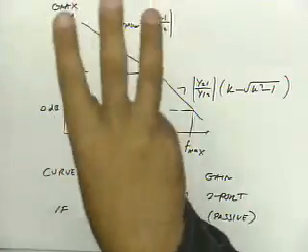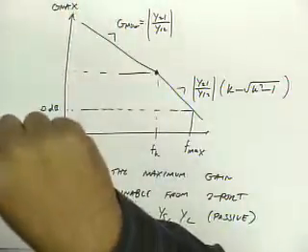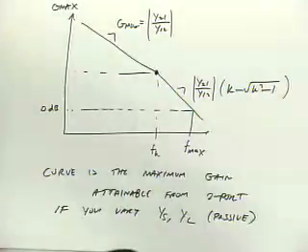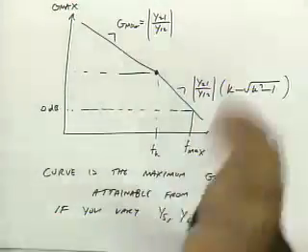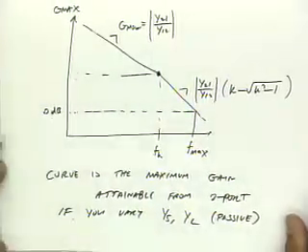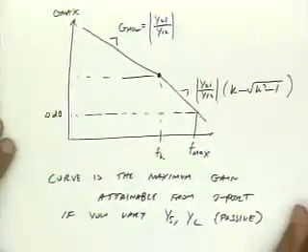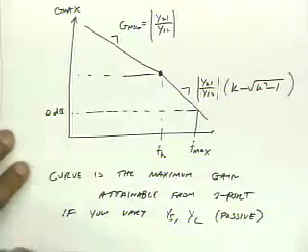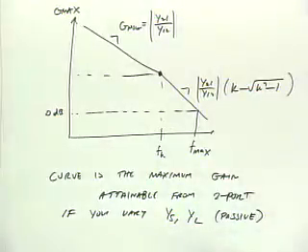So at very low frequency, your C mu is playing less role, but you have more gain in the device. Strictly at DC, you're right. The device is unilateral. Very good point. You will have a homework assignment where you'll take a real device and plot k as a function of frequency and plot these gains as a function of frequency, and you'll get some intuition for it.